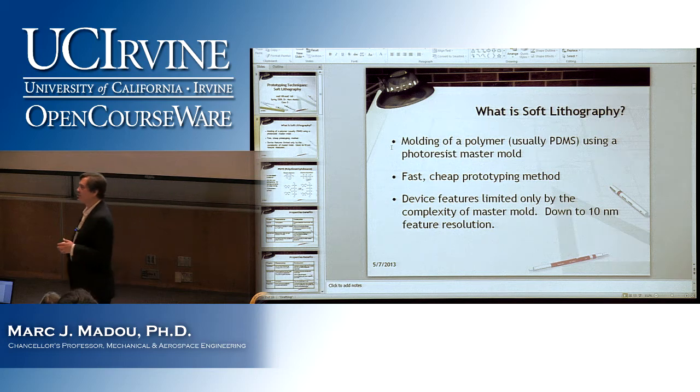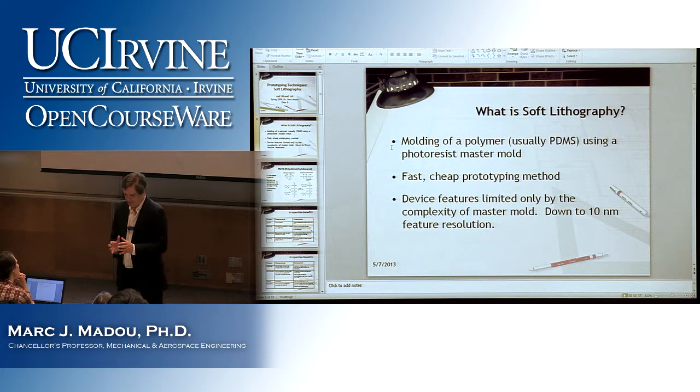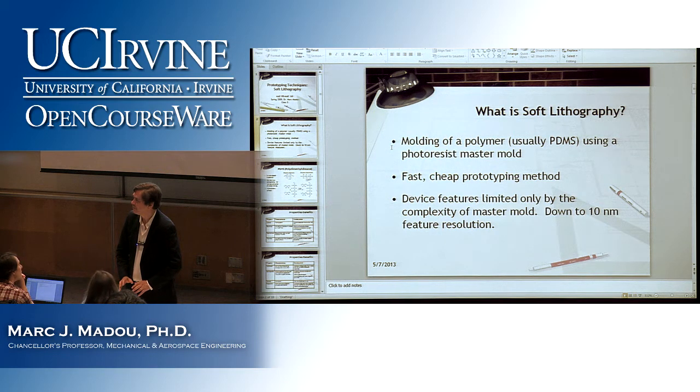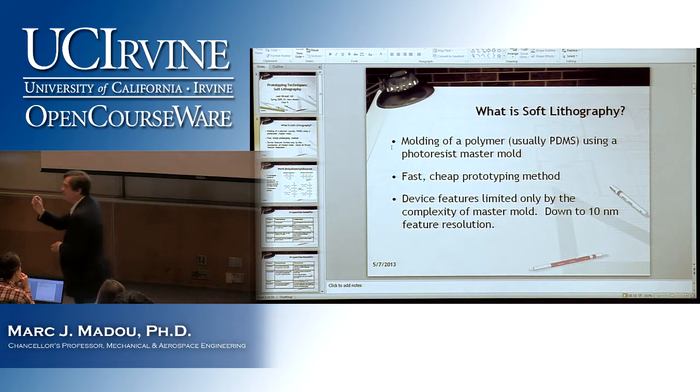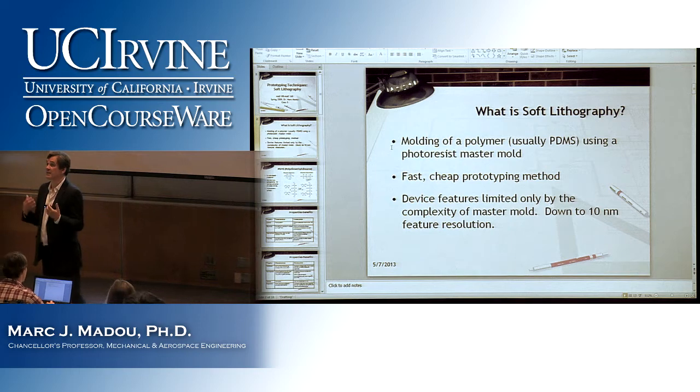Look, in manufacturing, if you have a mold and you make a part, you want it always to be the same, right? Now, if you have PDMS, which is a floppy material, and you stamp it, what do you think will happen? It will deform, and it will always be different. Yeah? And so, for research it's kind of fine, but if you want to really keep very tight tolerances, it won't work. But it's a fantastic research tool.